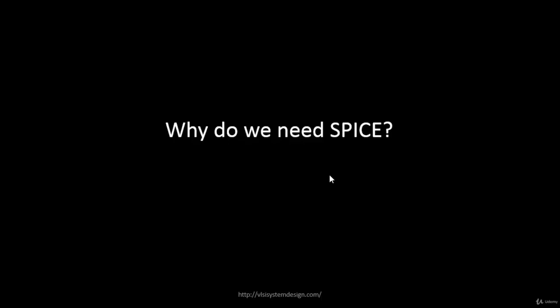And the answer is, this is a very important thing that needs to be done while doing a clock tree or while doing physical design flow. So let me try to answer, why do we even need spice? Whatever we have been doing till now about the clock tree, about timing, about crosstalk, is built on something called spice. If this would not have been there, there wouldn't have been any term called delays. And if you don't have delays, the clock tree, crosstalk, and physical design flow don't make any sense. So let's try to answer, why do we even need to do spice?